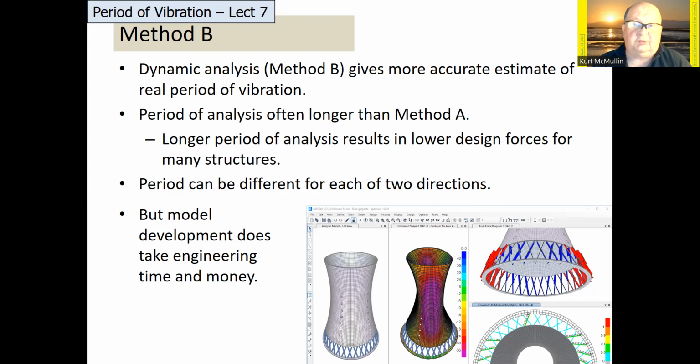It is possible to get two different periods in two different directions, but it does take time and money to develop a sophisticated structural analysis model, and on some projects it just isn't justified if that's the only thing you're using the structural analysis to calculate.